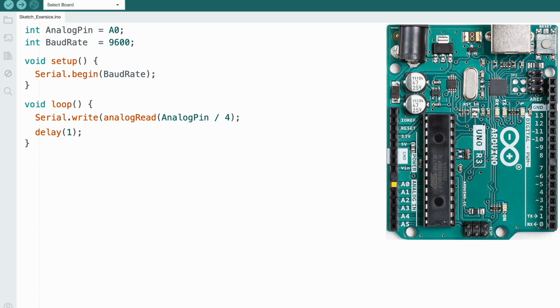The critical thing is Serial.write as opposed to Serial.println. And again, that's because we actually want to read values from the serial line so we can use that value in other aspects of our program that we're going to be looking at in a minute, rather than just reading print lines.